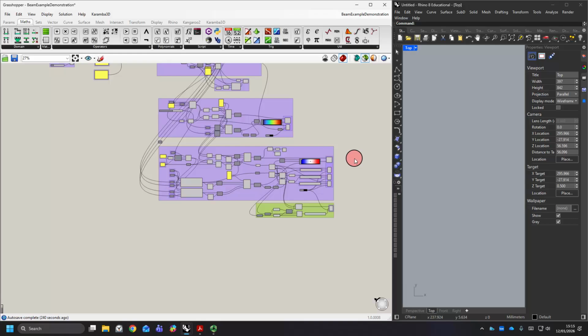One of the things that can be quite interesting is if you put in a simply supported beam, but then move the supports towards each other and see if you can reduce the value of the maximum bending moment. So you might be going from a sagging bending moment at the middle for a simply supported beam, to a hogging bending moment over the supports, and that's worth exploring to see if you can find the optimal position for the support. So that's one of the examples that I'll provide.